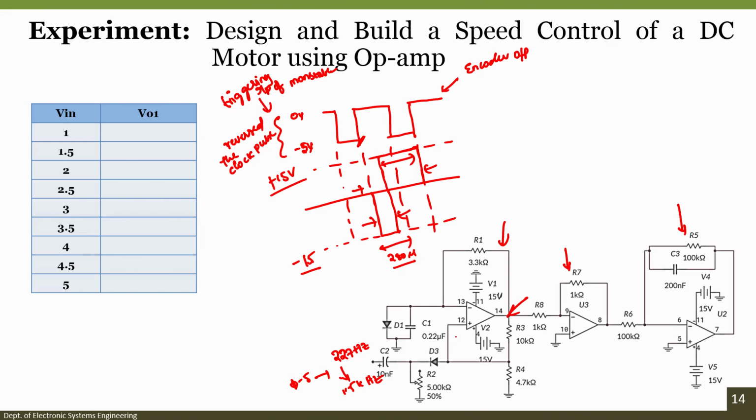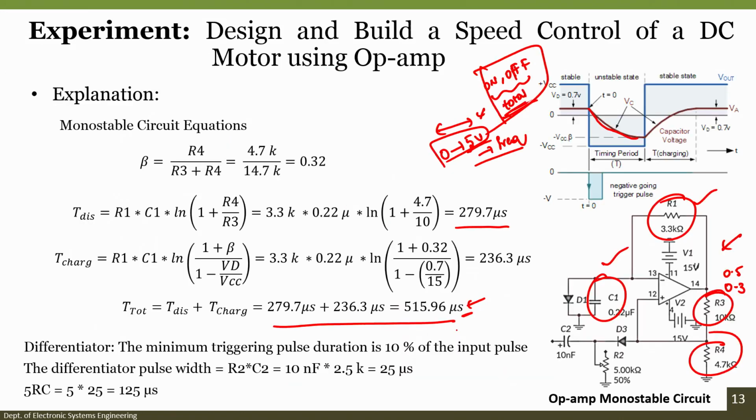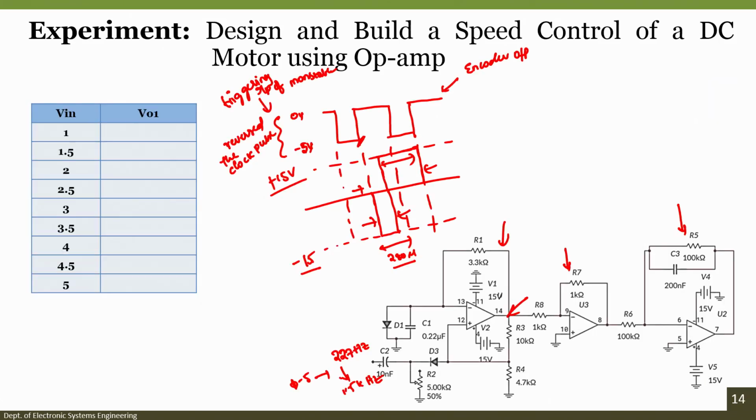But after considering everything, we have given a very big room in this case, where we require a total of 620 microseconds, but ideally 516 microseconds is the time required for the capacitor to charge as well as discharge in this case. So, we have plenty of time in this case to sustain those practical problems.